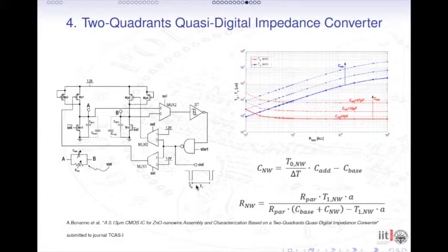But if we consider that we integrate the nanomaterials on the top of a circuit, and that the characteristic curve of a semiconductor nanomaterial can also be asymmetric, we probably need to measure the sensitivity of the nanomaterial in one quadrant of the IV curve and not in the other.